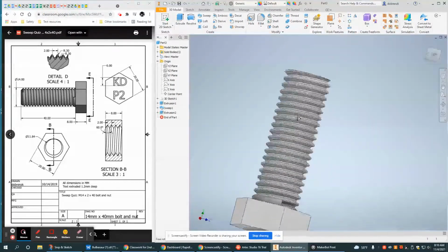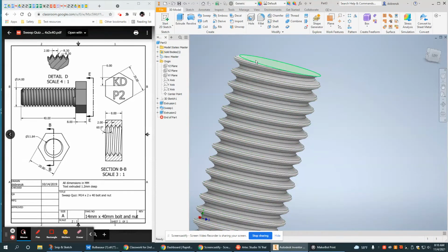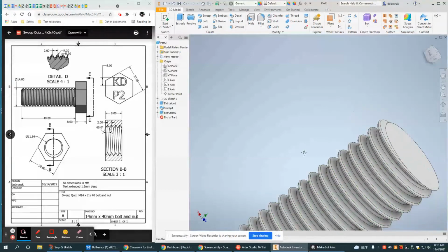Then one thing that is good to do, and I'm going to ask everybody to try, is to put a chamfer on this. Now, because of the spiral helix, we can't put an actual chamfer tool. It would have a hard time selecting what we want. So what we're going to do is cut this guy in half and just do a simple revolve cut, because in real life, that's what it would most be similar to.